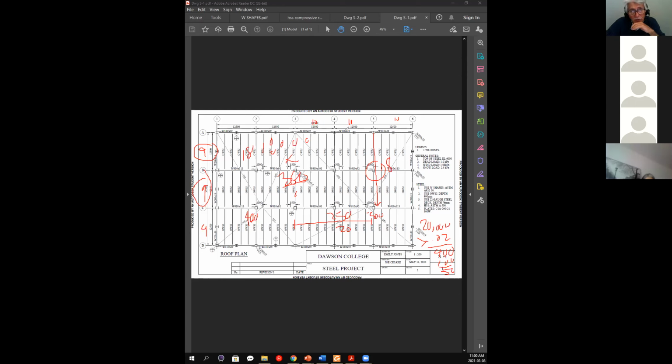And then after that, mathematically, you calculate what the other values are. They don't have to be the same from one side to the other. As long as you maintain 2%, that's the minimum. So here you could put 500, because we had the 100 millimeters for the shoe. And here we said 360, plus 100, so here it would be 460.